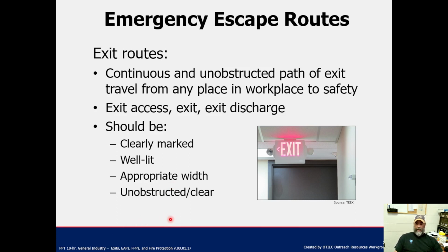You cannot have things in front of doorways. If that is an exit route, you cannot park a cart in front of the doorway. They're also required through OSHA regulations to have exit signs, not always lit, but they have to be clearly marked. You have to identify that it is an exit area.